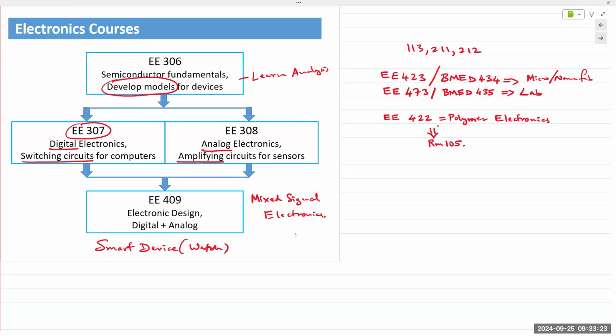To give you an idea how small we're talking about, in a room like this, if you take a small cubic centimeter of space, there's about 1 million or 2 million fine particles. A comparable clean room will have less than 10. And higher level clean rooms will have less than 1. So that's class 1, class 10, class 100, class 1000.